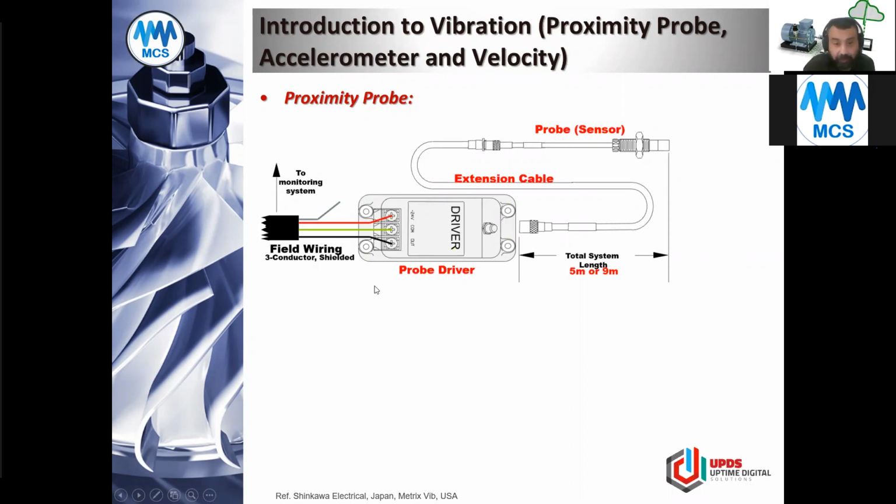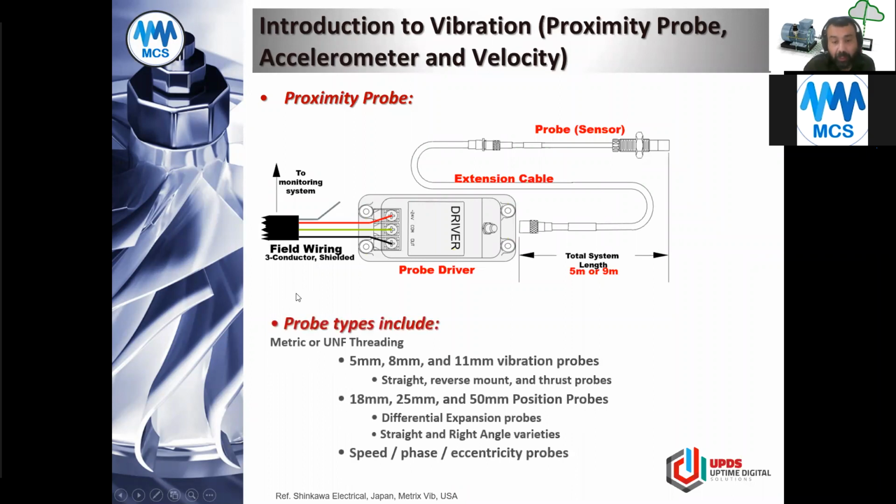Proximity probe, what I mean. What is important about the proximity probe? To know exactly what is the provision of it and what is the tip size. When I say the provision, it is the inactive length, where you can see the thread here, when you can control the thread or the installation length. It will be written in the technical data sheet of the sensor, and the effective coil tip.